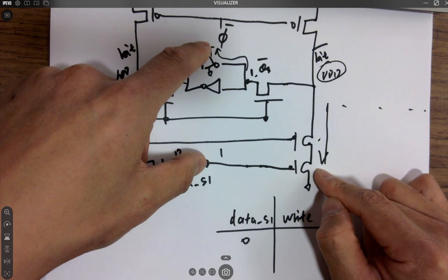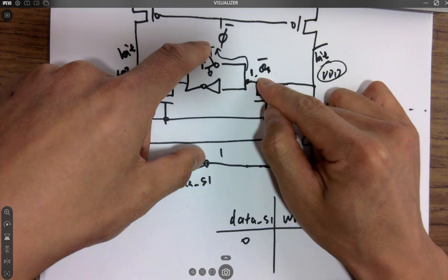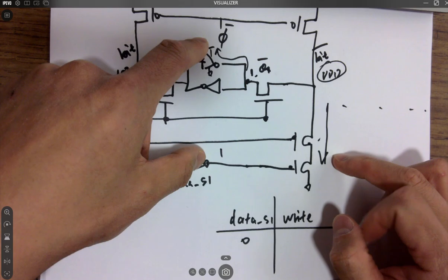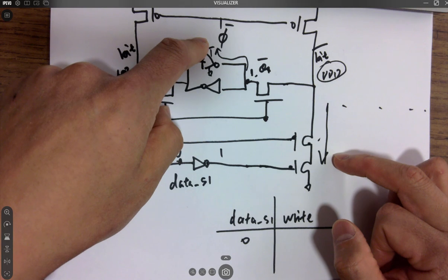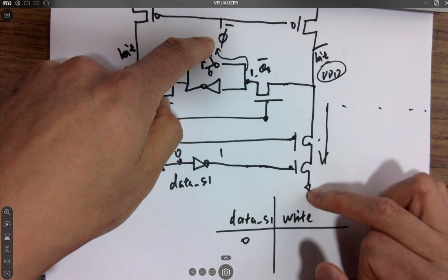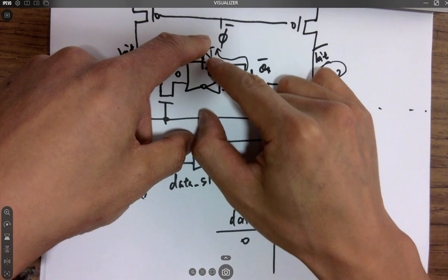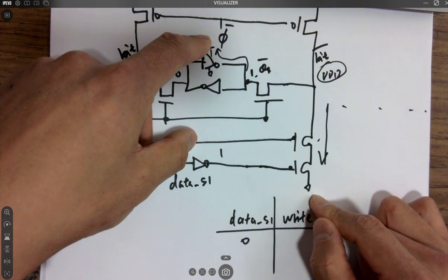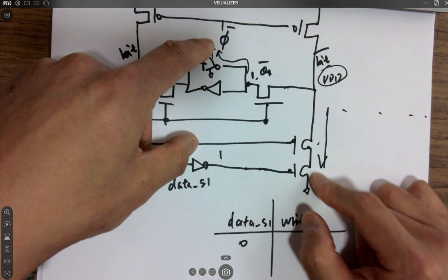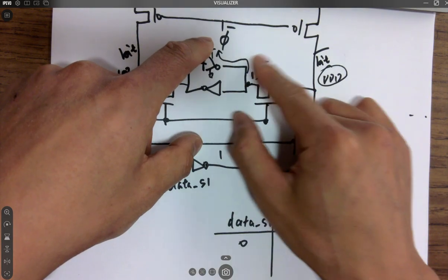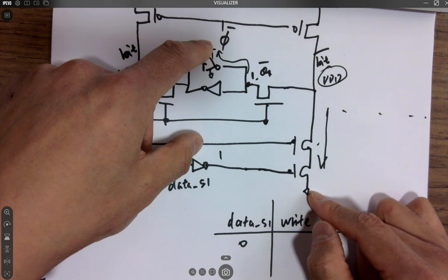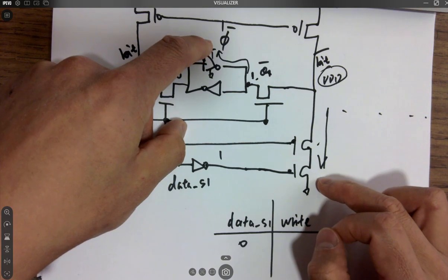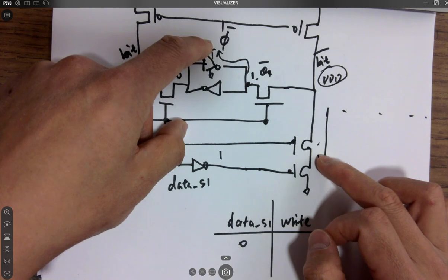They are both on, right? However you want to flip it, what's the design consideration over here? They are both on. VDD seems like it's shorted to ground, but actually it's not because there is also channel resistance over there, but it's very close. However, it's competing. It all happens really quickly, so we don't have to worry about the power consumption over here. Do you get a voltage drop then? I mean, no, the design consideration to make this happen.